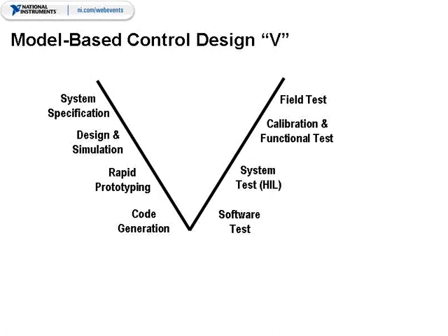In the design of embedded control systems, where you can use model-based control design, the V diagram is typically used to represent this process. The details of the V diagram are not that important today, but what is important to recognize is the left-hand side of the V diagram represents the design portion, where you're creating the control algorithms and the logic that will go into the controller. This terminates with the code generation step down at the bottom, in which software is developed and embedded on an actual controller to go into the embedded control application.